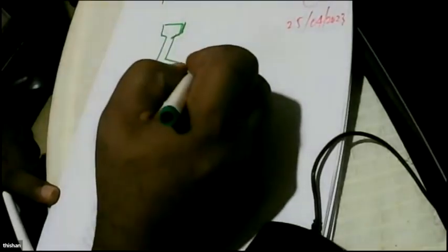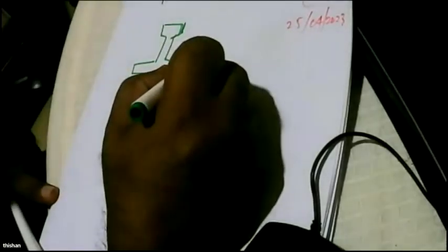So what we have is a beam. What is the advantage? Up to 18 meters, we don't need formwork. So we place this bridge beam, and this beam is done in such a way that when you are doing the construction, you don't need any kind of formwork, right? So we place the beam, and you place the next beam.